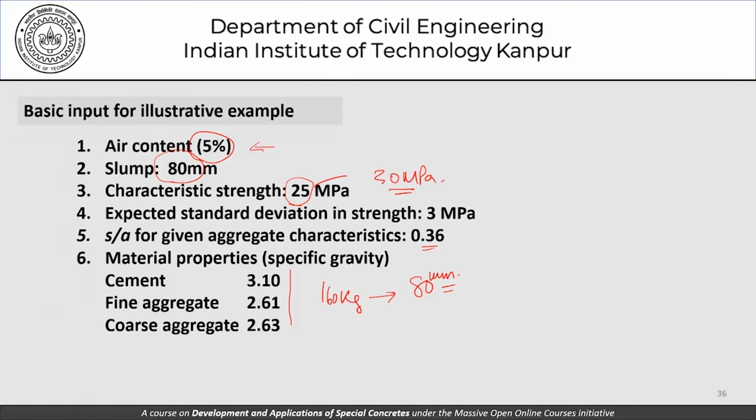This is something related to fresh concrete. As far as the strength is concerned, we may have to wait for 28 days before we know whether or not the 50% water cement ratio that we used actually yielded the 30 MPa that we thought it would. If it does not, then we may have to make an alteration in our water cement ratio itself. Those are the kind of things that we really need to be concerned about.